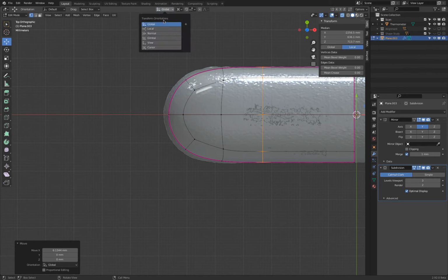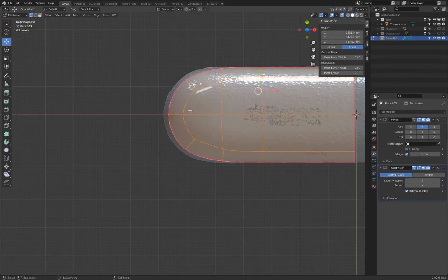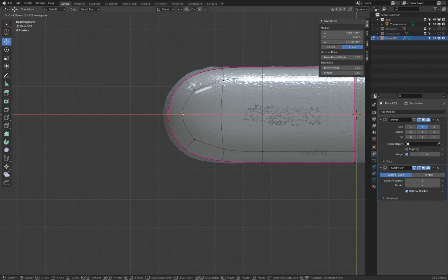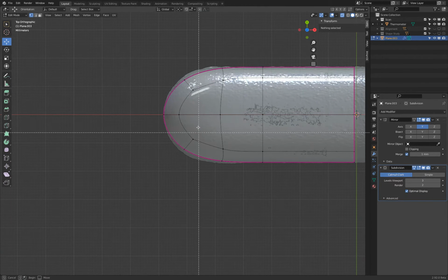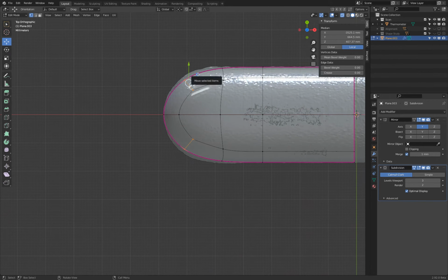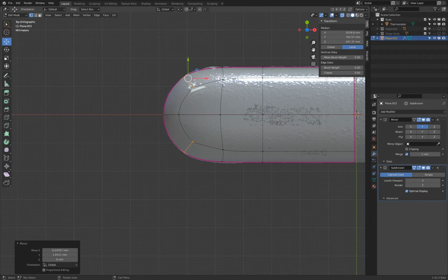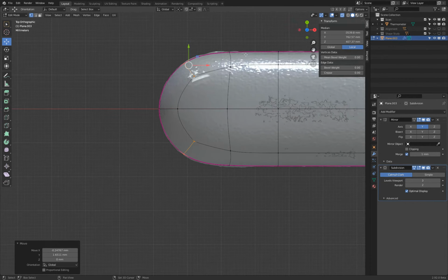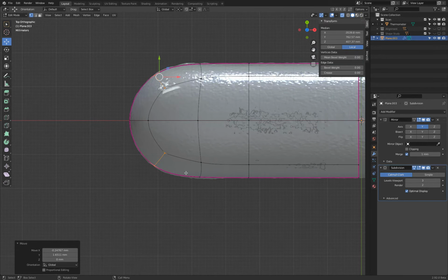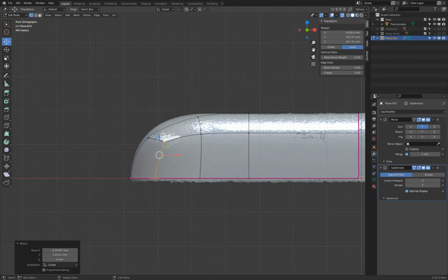Let's clean everything up better. We go to bounding box, AA, B, select this, and we stretch this to there. AA, B, select this. We have to work on the upper part. Stretch this to there. And that kind of like doesn't look too bad. Here it follows it good. Let's go to a side view.